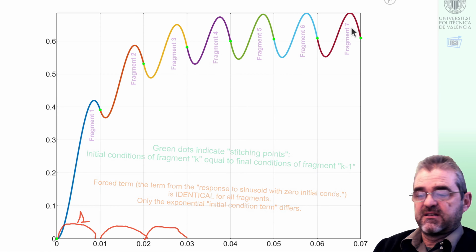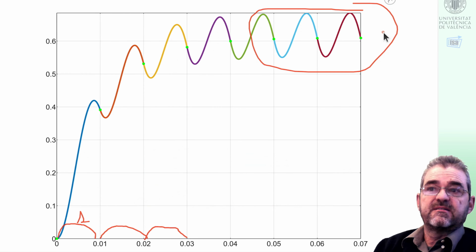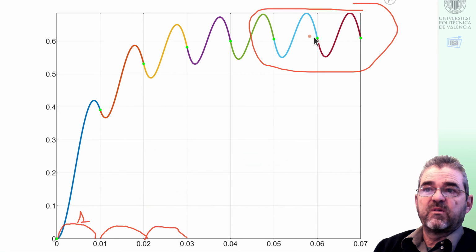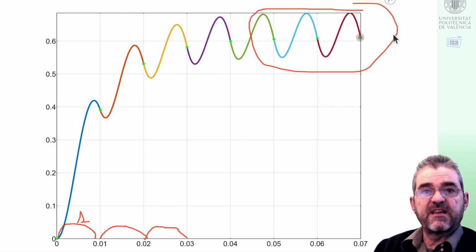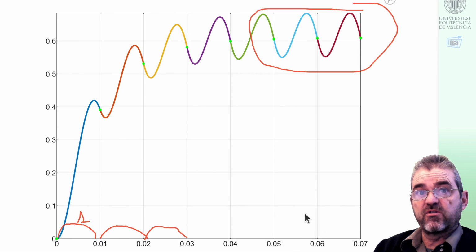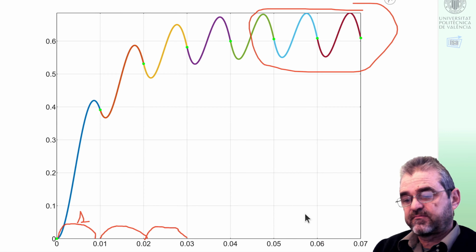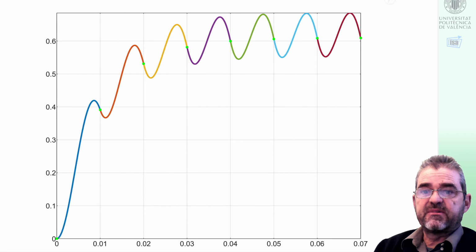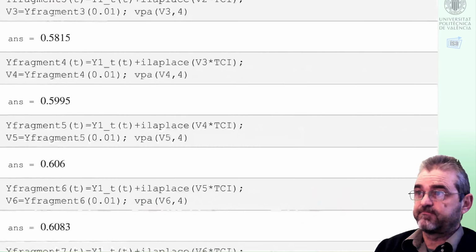As we can see, we reach sort of steady state where the green dots always have the same level, and that would be the non-sinusoidal steady state. It is non-sinusoidal because the input is a periodic signal, but not a sinusoidal one, so the response will have harmonics. And we will next compute the formula of that steady state. But let us first recap how we computed this.